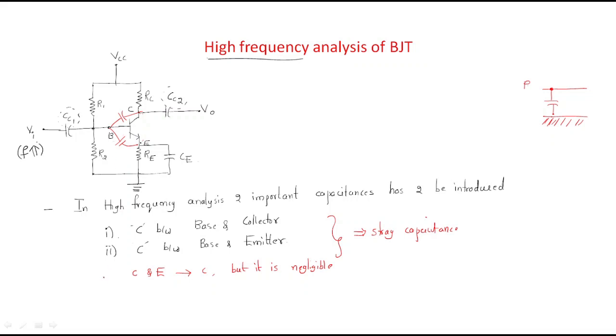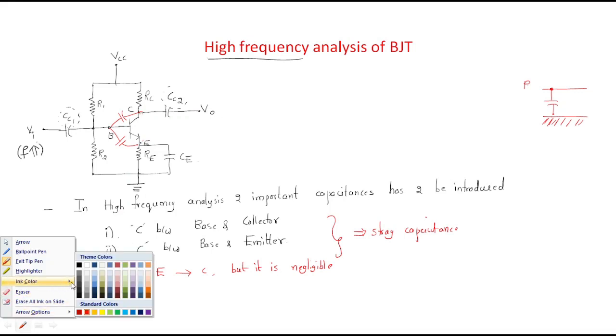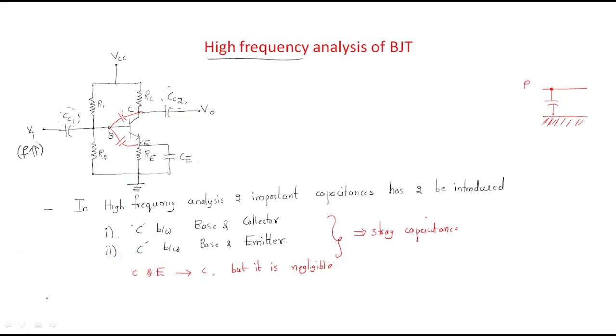Here we need to do the AC analysis. You know that for AC analysis we have to short all the capacitances, the coupling as well as the bypass capacitors.